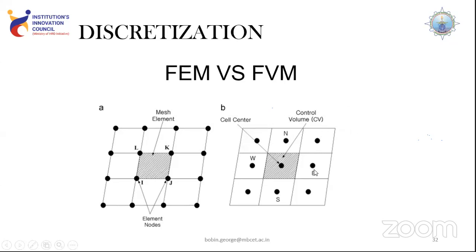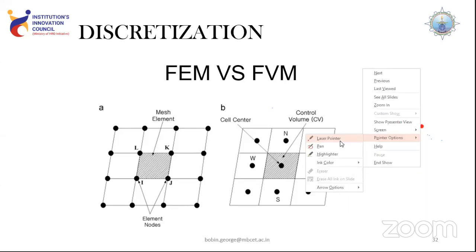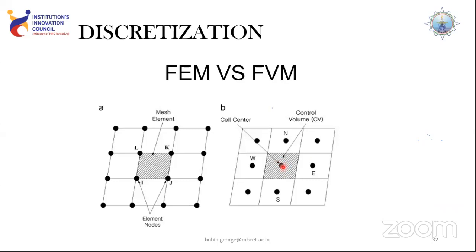and applying that equation onto the cell centers, where the conditions nearer to any one of the cells will be known. With respect to that known condition, we assume the initial flow field. We assume that this is the initial condition and we solve the equations based on that, on the cell centers themselves, so that you get an accurate flow field of the analysis.